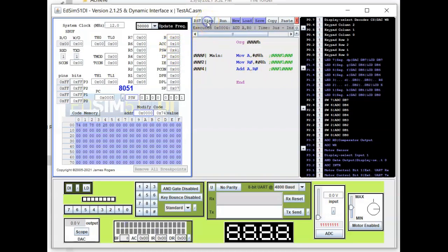Let's step it. Yeah, so it's 10. That's the hex equivalent of this binary number here. That's the result of the addition. And because there is a carry over from bit 3 to bit 4, the auxiliary flag is set. All right, there's a carry over from bit 3 to bit 4, and that triggers the auxiliary flag, the AC flag here.